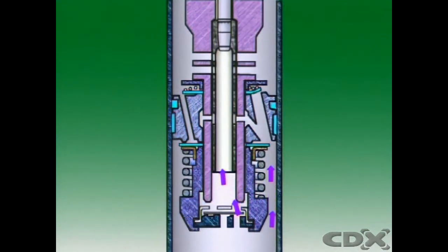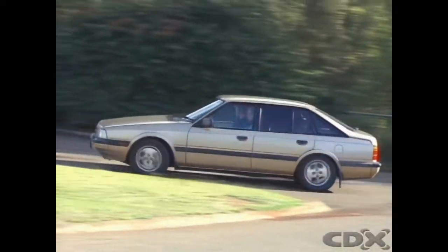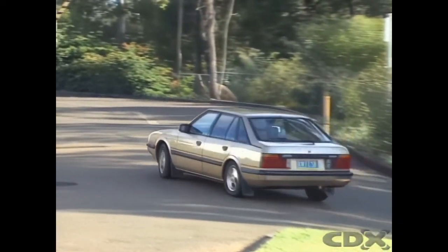In this position, all orifices are open. Oil can flow more easily through the passageways in the piston. Only a small dampening effect is applied to the oil. This provides a dampening force that emphasizes ride comfort when traveling at low speeds.